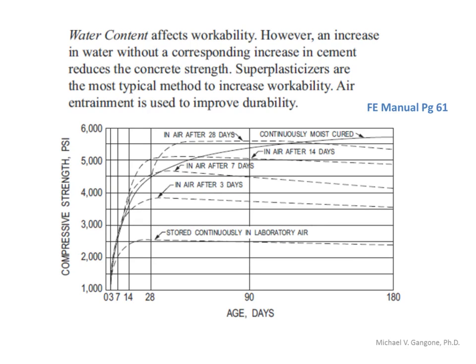All right. This particular table is one of the reasons I put it in here, just to show you what effect curing has on concrete, and also what effect time has on concrete. So curing method as well as time. You can see over time as we reach about 14 days, we've achieved a lot of our strength within the first 14 days of curing. After that, we gain a little bit more strength, and then things start to level off. Over time the strength continues to increase, but the amount it increases reduces significantly after a certain point.